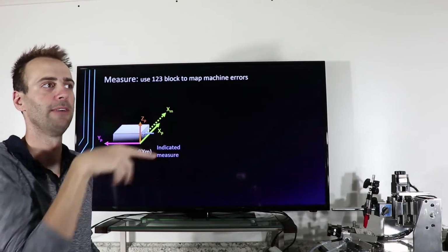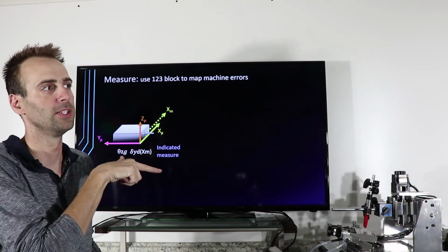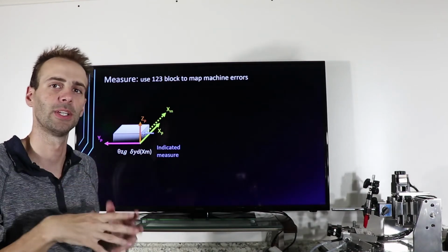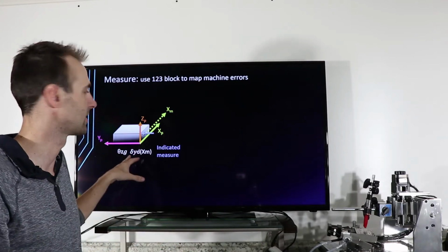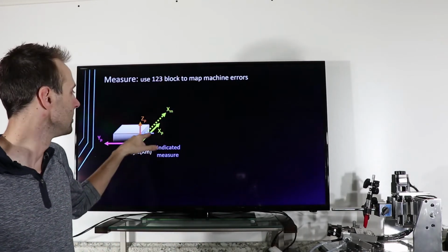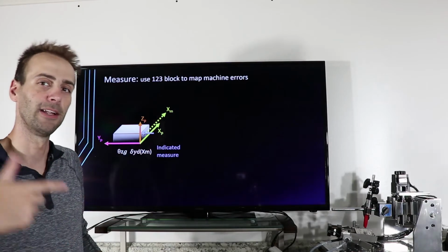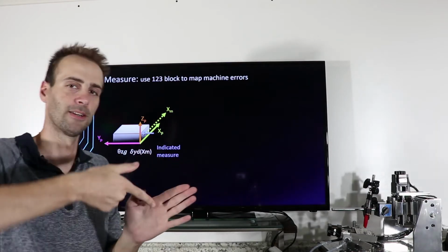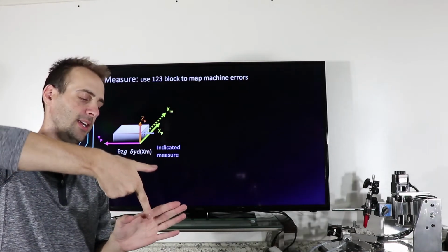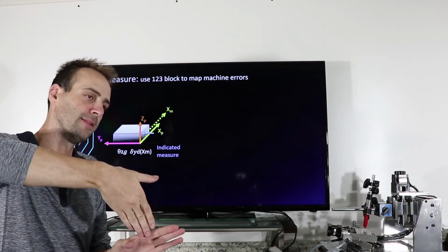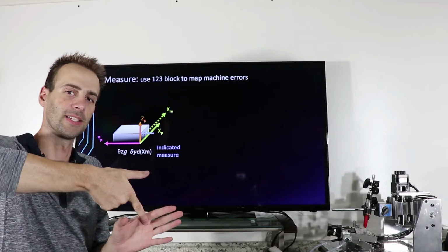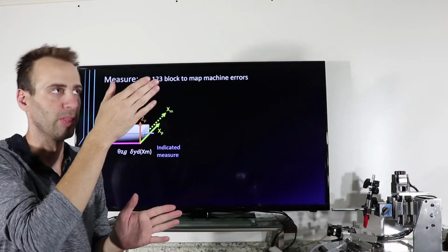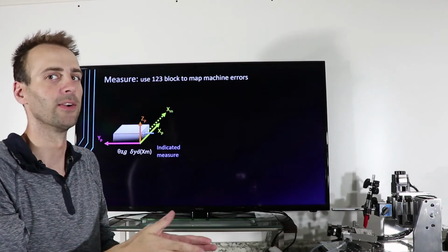So however you have your dial indicator, as long as you're looking for that average line of motion, it's fine. The scale is completely arbitrary, but in software correction, it's not. So you have to make sure that you're indicating perpendicular to the face, okay? So the wiggler needs to be in the plane of the face, with the wiggler on the face itself, and with the wiggler sort of straight down, okay?